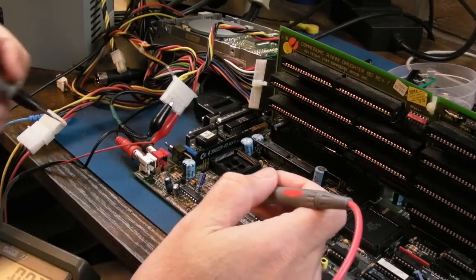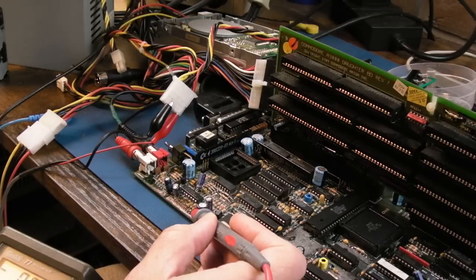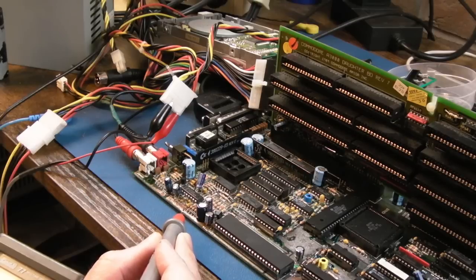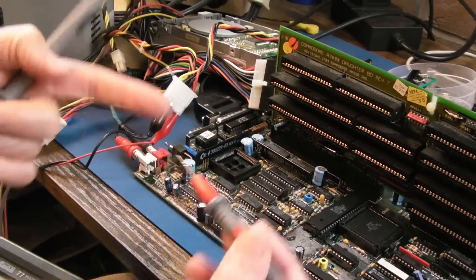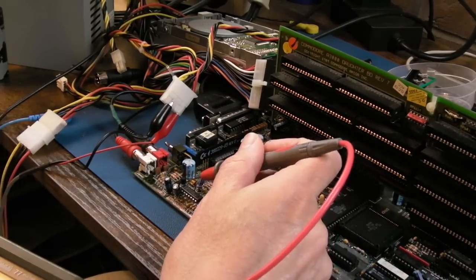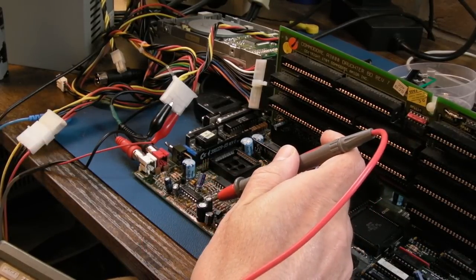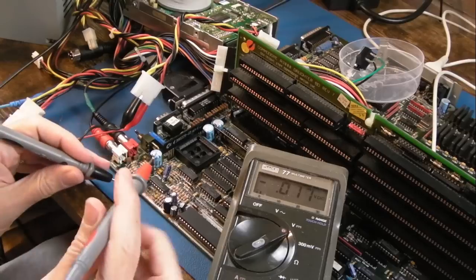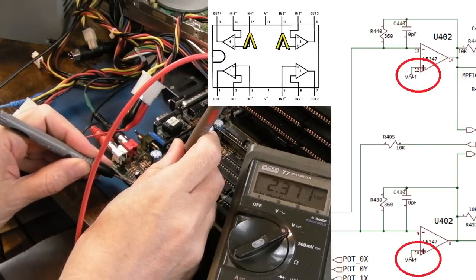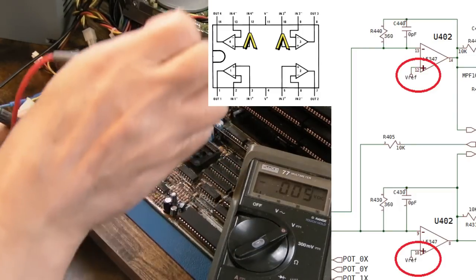The two resistors here, 1.2k, opposite each other, and the top point on this one goes to ground. The bottom point on this one goes to a VCC rail, audio VCC, which was about 4.7 volts. The centre of the two resistors, this side and this side, should join together and go to the third from the right here and the third from the left there. They were not joined together, that's all it was, so I just put a wire from that point there to that point there on the underside. If I just measure the third from the top right on the op amp, 2.37 volts, there we go. So we've got our VREF, it's roughly 50% of the 5 volt rail there.